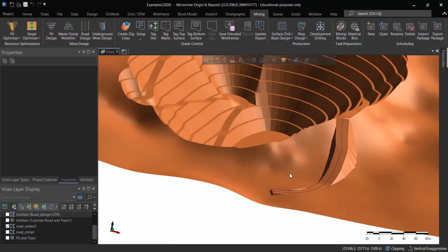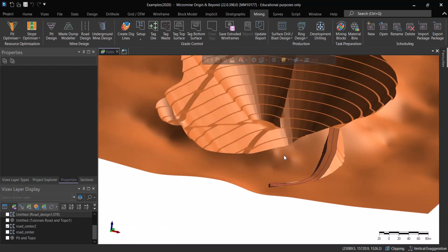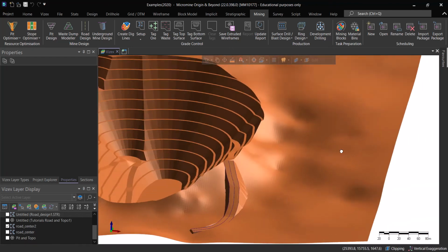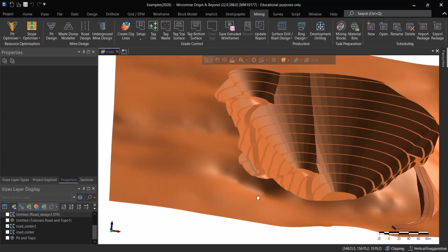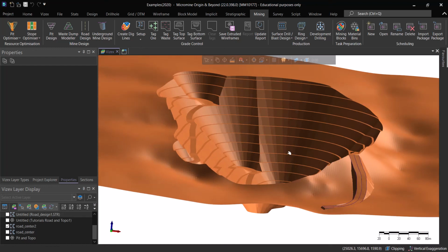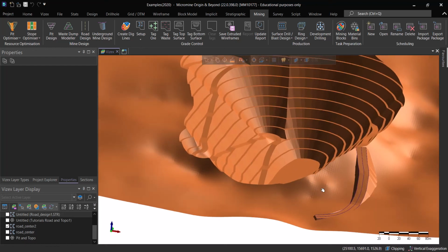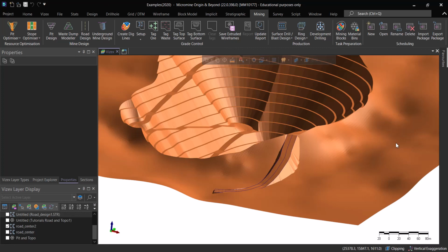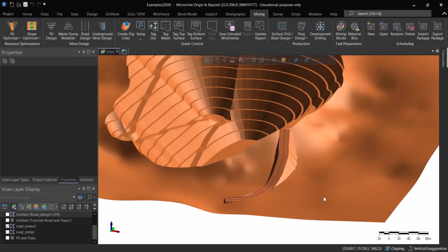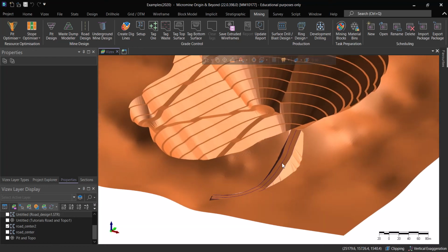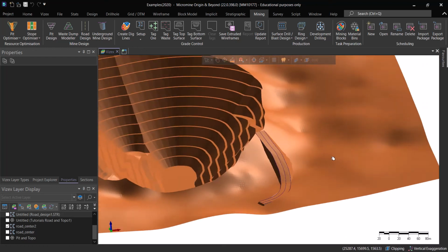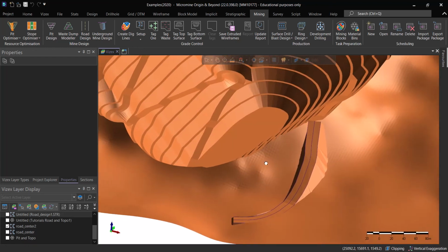So this really depends on the criteria that you want to create. And if it's a flat area or nearly flat, it doesn't matter if you just drop that onto the topography and do the design the way you want, or with the first method. But usually, in most cases, in locations where we have steep slopes and so on, we need to keep the slope of the center line constant, or we choose the right slope for that. So we design the road in the best way.